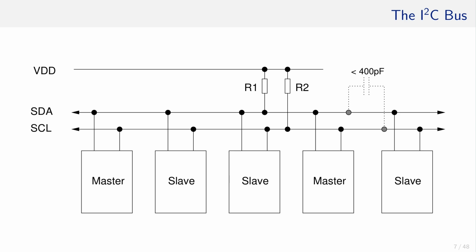If no device is connected, their potential will be equal to VDD, since the source will charge the wires through those 2 so-called pull-up resistors. So imagine the supply powers the wires through these resistors, hence both of them are idling in a high state.